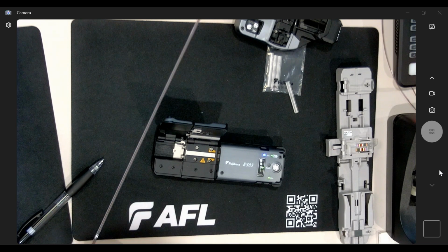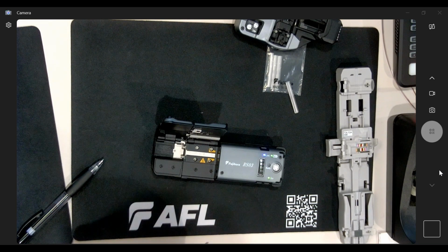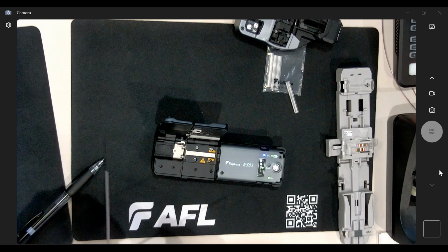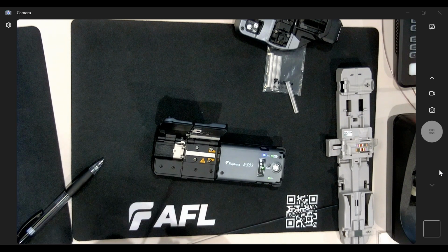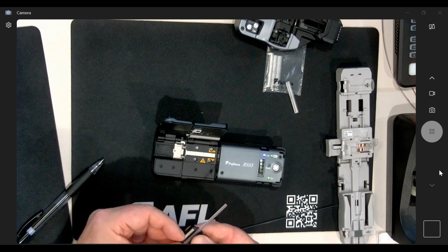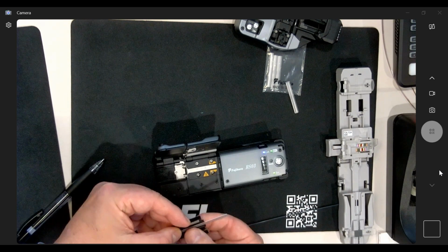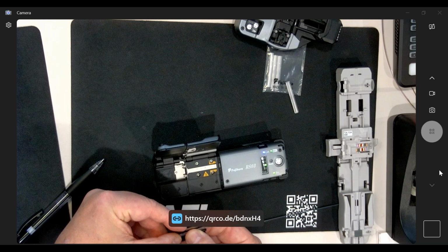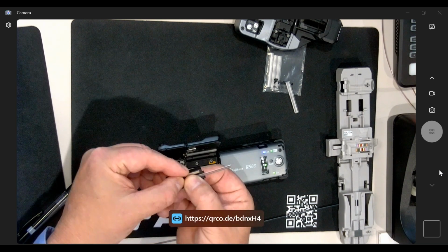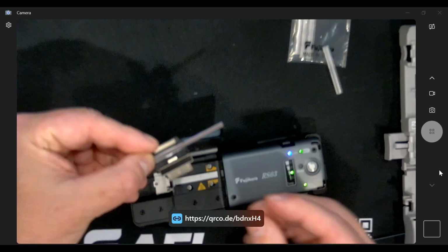In this particular case, I believe I have the mode in the Fusion Splicer set up in SM Auto. Since I'm doing a traditional matrix material, this Corning ribbon, a couple of things about this. This is kind of old school, very easy to operate. And I'll make a quick strip and prep for you and kind of describe. And I always use this during my initial training with my customers because I want to spell out a couple of things with this. The first thing is my strip length. I have no concerns about going a little bit long with the fiber holders you see here. Drill down, look at the closer view.